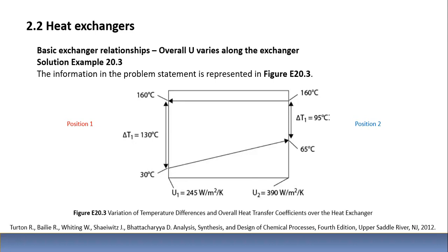We already saw that counter-current operation will give us a greater delta T logarithmic mean. So in an exam, you guys don't need to solve the problem using a co-current configuration, or even ask in the middle of the exam what configuration should be considered. You can automatically consider a counter-current configuration, just like has been done in this example.